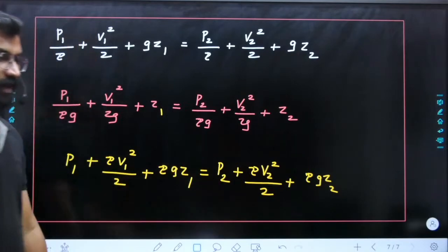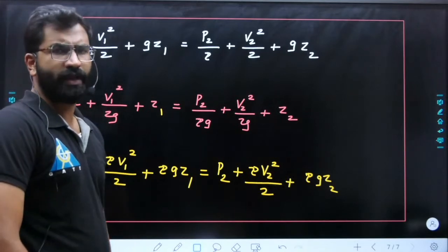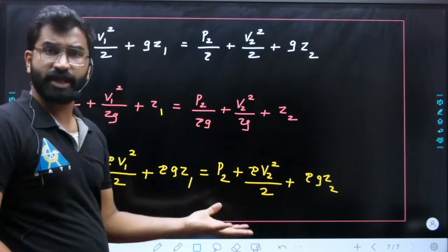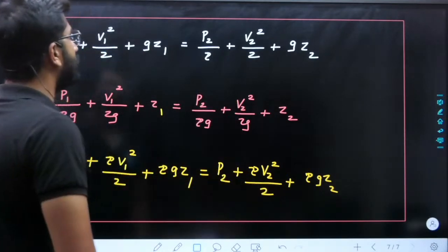Okay, so this is very important. Always remember, it should be steady, and it should be incompressible. These things are very, very important. Now, why should there not be a heating and cooling section in the Bernoulli equation along a streamline? Because whenever there is a heating and cooling section, density will change, so the incompressible assumption will go off. Those things you need to remember.